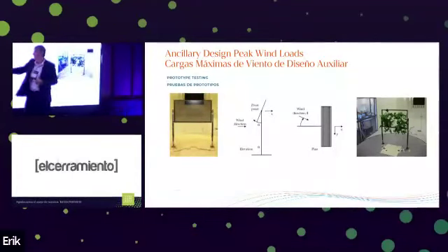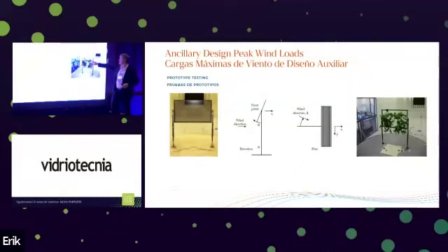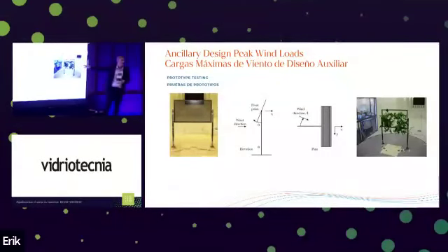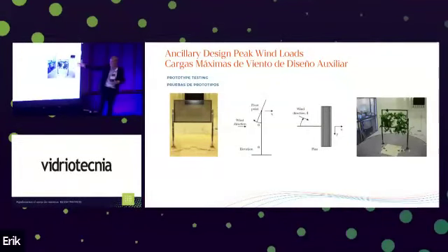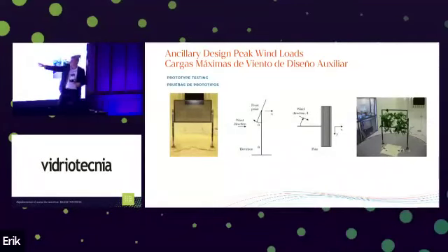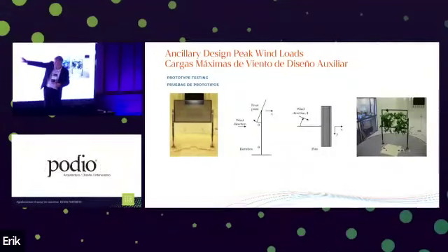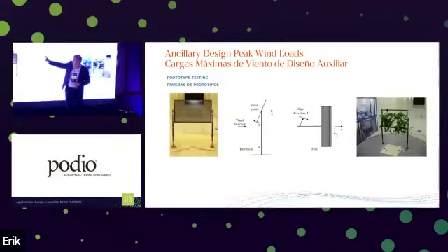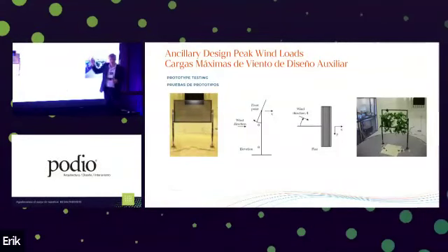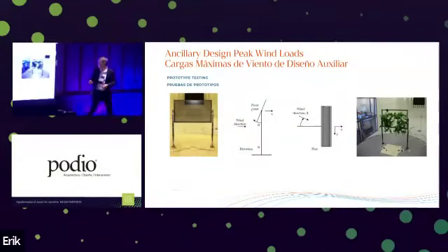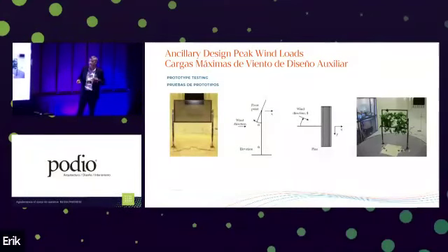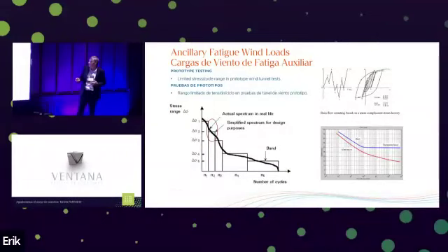So we have a screen here. There's even some planting here for a green facade. The client wants to know what the drag coefficient of the vine is. So to give the full drag coefficient information, we test through a range of tilts and yaw angles, and we can define that totally in the wind tunnel. That's all right. Again, if it's a quasi-static load, that works quite well.